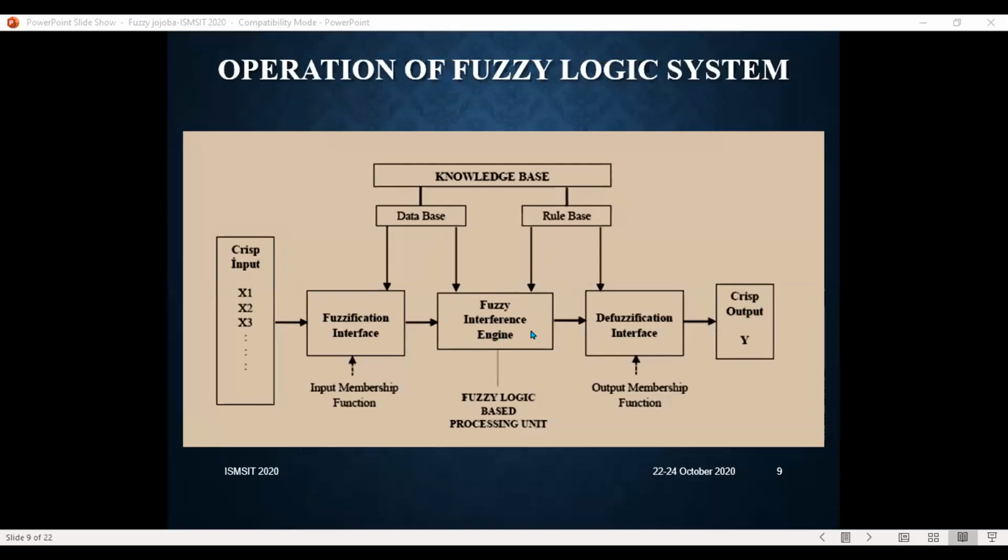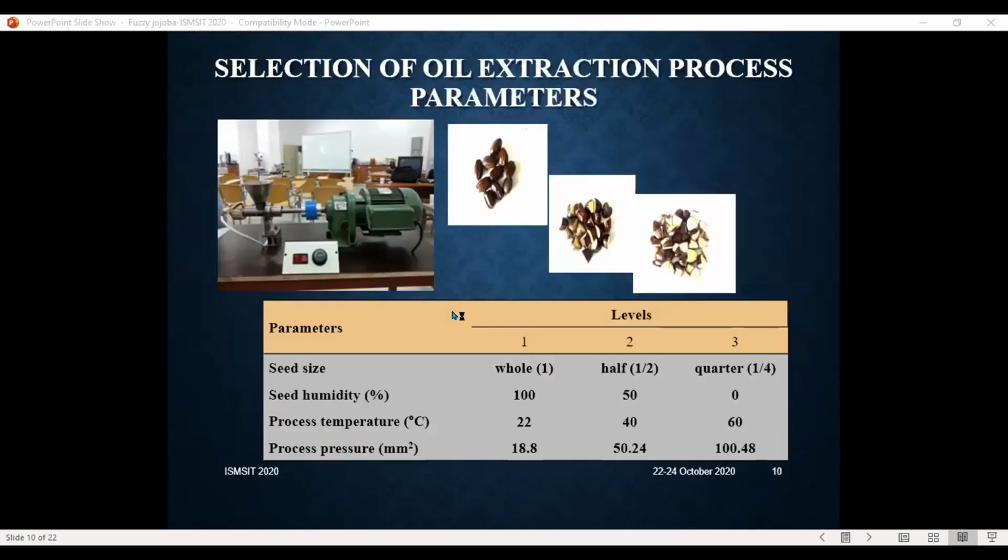We are teaching the computer how to think, what the relation is between input and output, and we usually use fuzzy logic for non-linear relations. Then the fuzzy inference system calculates, and you obtain the crisp output data of your system. By this process, you are checking the error. If it is small, it's okay, your system is working. Otherwise, you turn back and reconsider the membership functions.